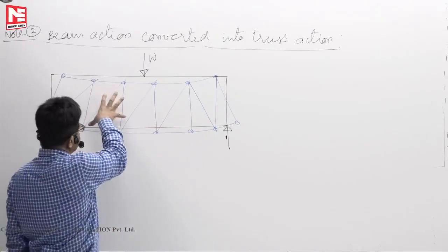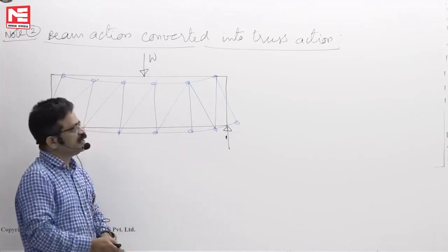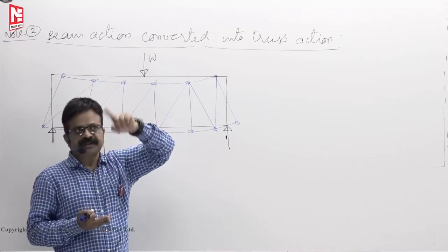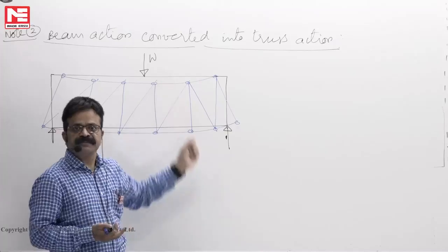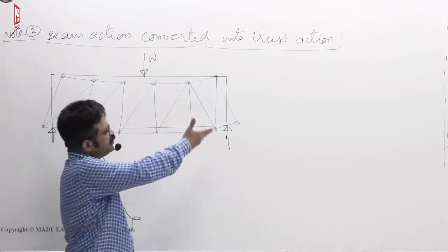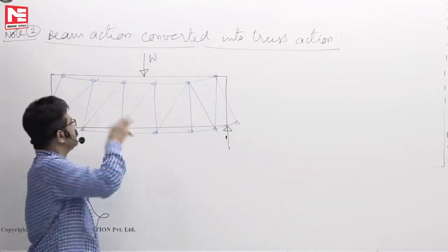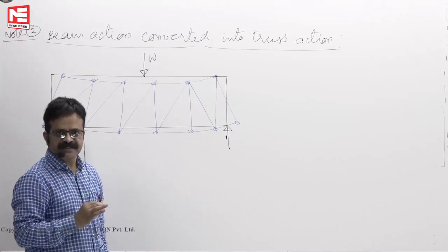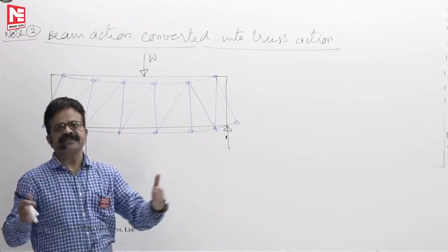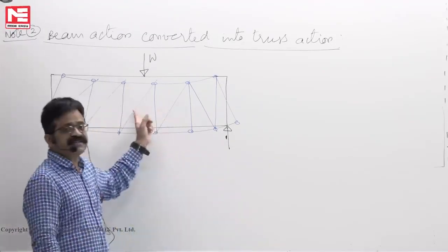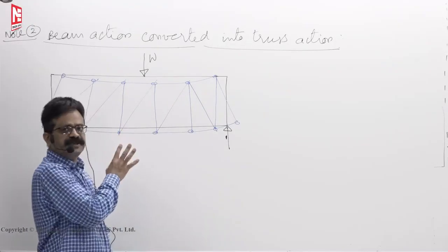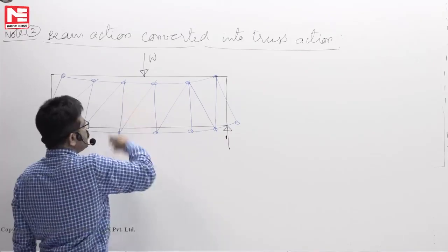So, this one is everywhere holes only. There is a simply supported beam, sir might have told you, maybe depth of the beam around 600 mm, that means 60 centimeters. Earlier problems we have written 4 meters, that means one floor height you can have. That means weight also very less because everywhere only wires like construction is there, everywhere holes only. Weight is minimized. So, a beam which can resist the bending moments for a span of 5 meters, let us say, these can resist up to 30 meters also. You can go for more spans without any intermediate columns because weight is less, height is more.